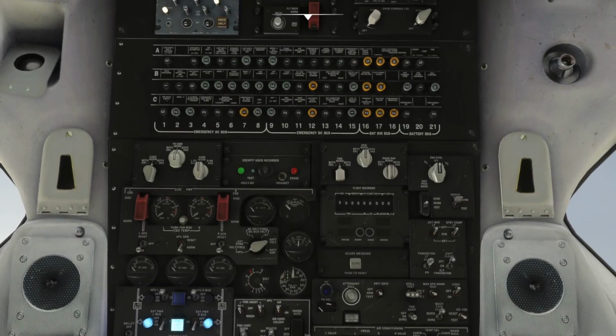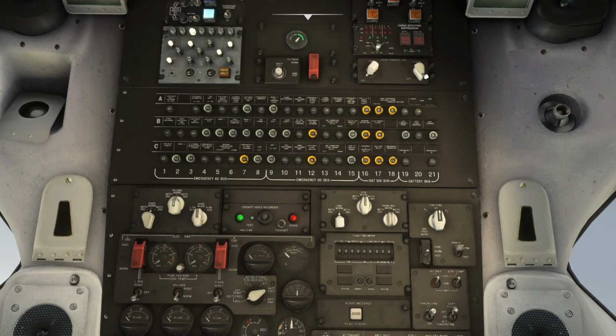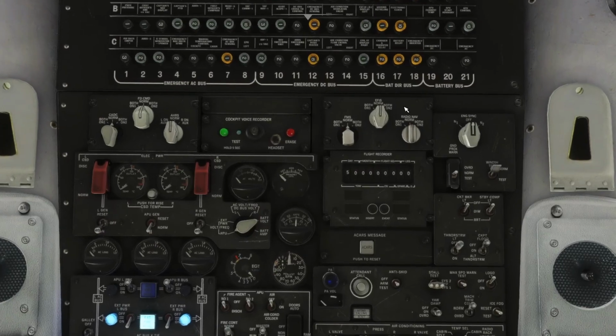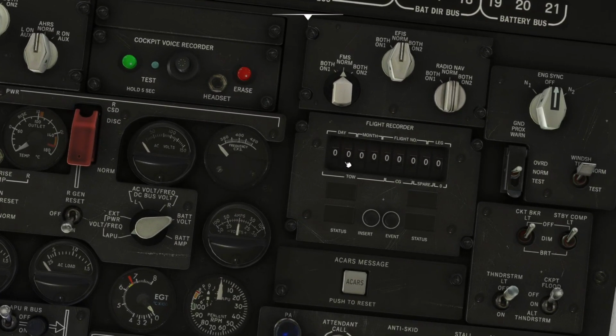Okay, so we're not going to use panel lights right now. It's still day out, but these are for the overhead lights and the overhead floodlights. I guess we'll put in the flight recorder information. So it's the 2nd of May. So that's day 2, month 5. And that flight number is 1623. And you can go over a bit there for a 4-digit flight number, and it's leg 1,